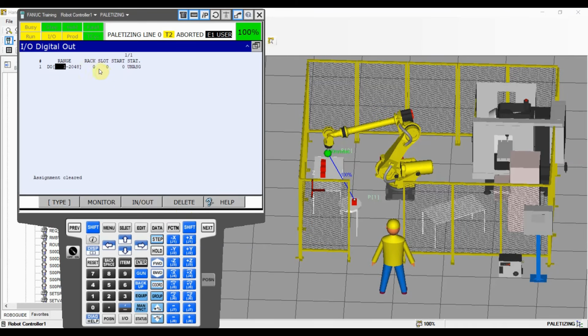So how do you set it up? Let's say we're using a Profinet to communicate with the devices. Profinet uses rack number 99 and rack number 100. Rack number 99 is used to communicate with the PLC, rack number 100 is used to communicate with the devices. So we're going to use 512 outputs to communicate with the PLC. So we're going to use rack number 99, slot number 1. We don't want to use offset number 1. This is going to be our PLC communication.